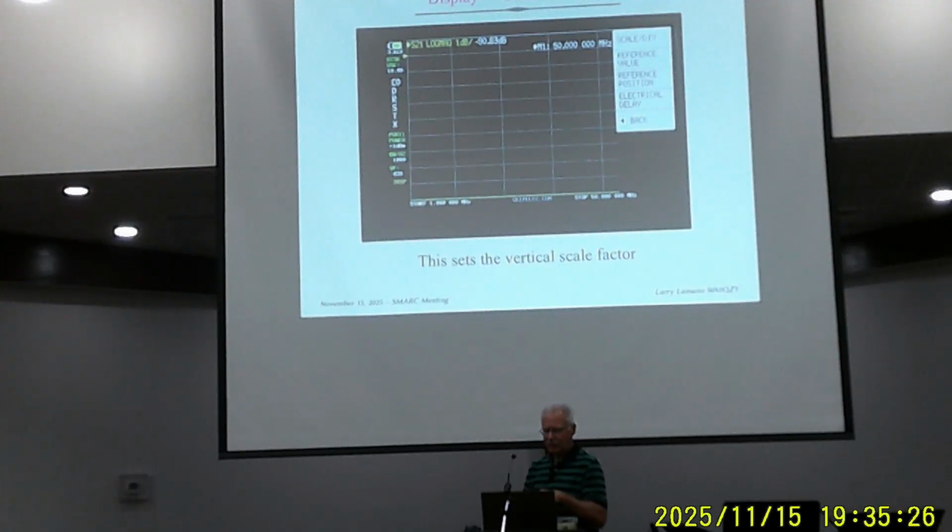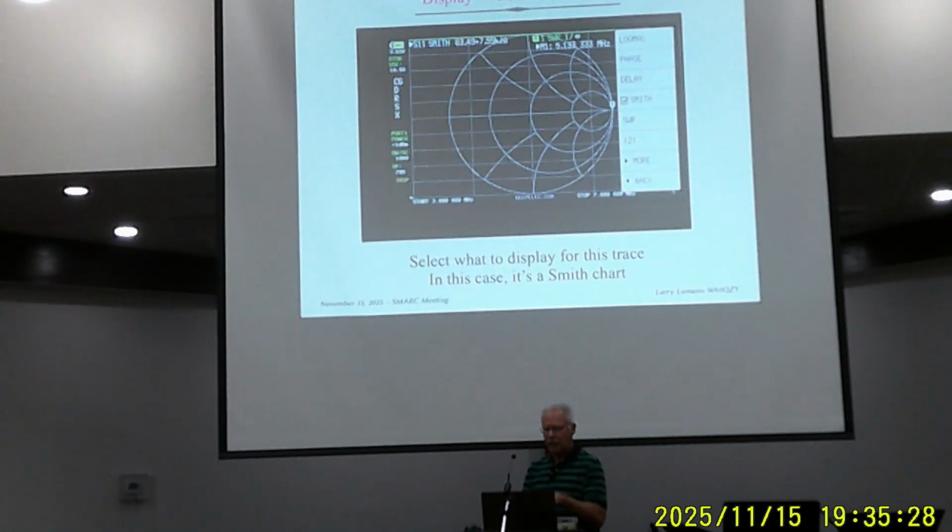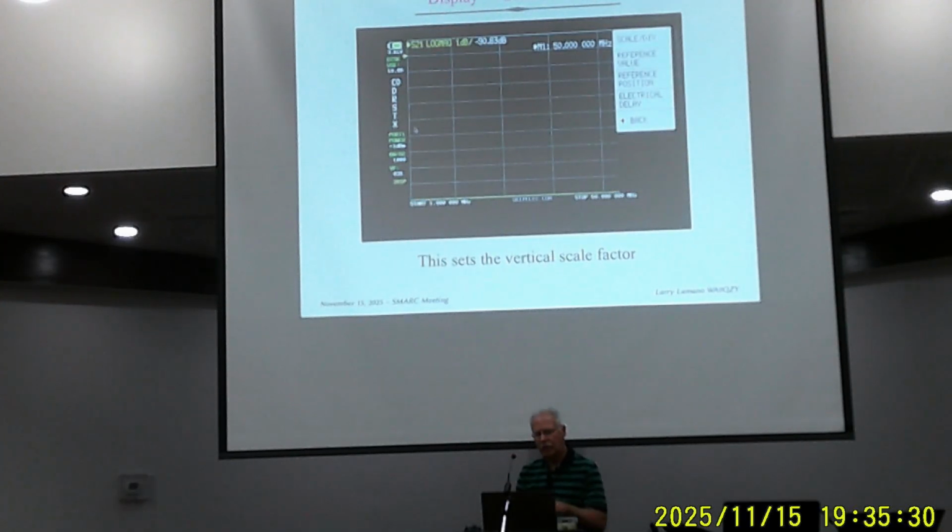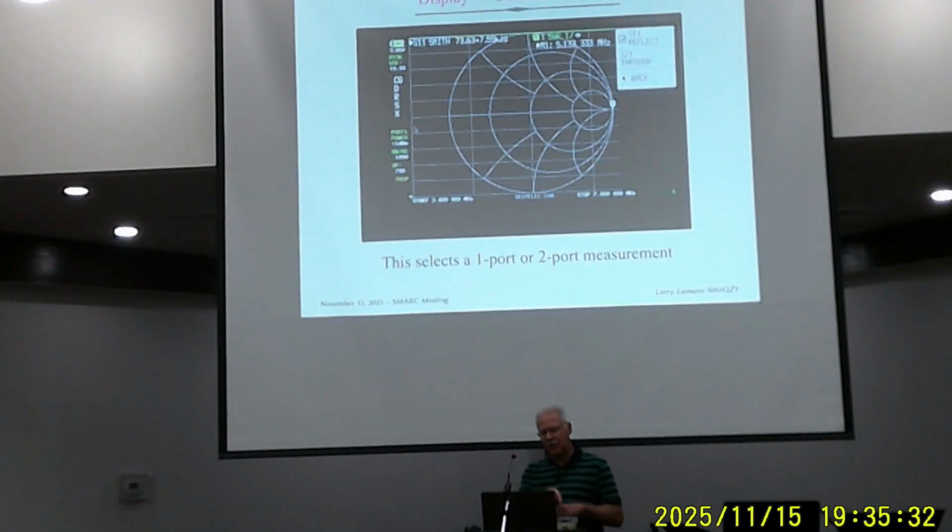And then after that, we had to go back again. Whoops. You go back again, not forward. You go back onto the menu, and it's the channel submenu, and you just say, is it a 1 or 2 port measurement? So they're all pretty straightforward. You say, I want trace 1, I want it to be SWR. The scale you probably don't have to mess with, and it's a 1 port measurement. So it's really that quick to set the thing up.